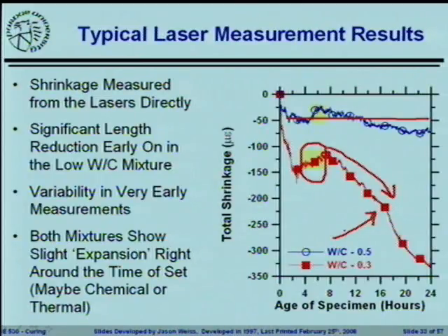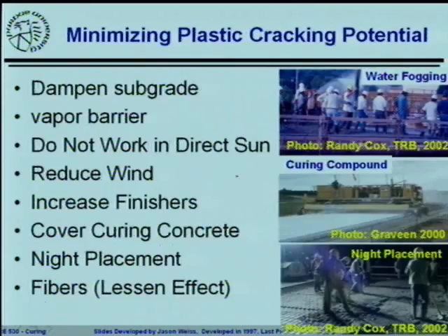All right, there have been studies in Japan that have shown even concrete that's completely underwater can undergo enough autogenous shrinkage that it can crack. So you can completely be ponding a concrete, have it completely underwater, and it can still crack because internally it's drying out. The basic idea is it's drying out internally faster than the water can get sucked into the concrete. So these are some things that you need to be worried about, especially when you get to very low water to cement ratio mixtures. Now, what are some of the things that you would do?